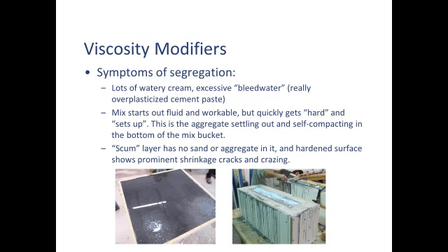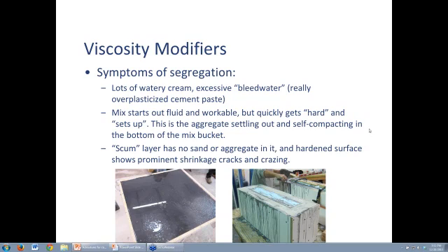Symptoms of segregation. Very, very common. I see this a lot with people just starting to use the very powerful super plasticizers, or any plasticizer when they use way too much, but especially the polycarboxylates. They'll put it in their mix, and as it's in the mixer, it's splashing. The concrete's just flowing around. It's gorgeous. It's wonderful. And they dump it in their bucket, their dispense. Maybe it's a wheelbarrow, maybe it's a mortar pan or something like that. And they start scooping it into their forms, and very quickly, all of a sudden, they think, oh, it's setting up on me. Well, what's really happening is you're getting segregation because they used too much super plasticizer and they didn't use a viscosity modifier.